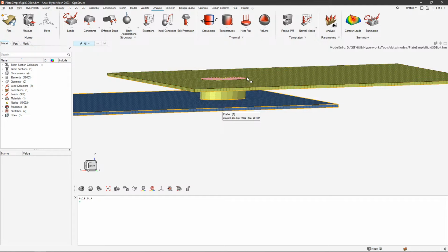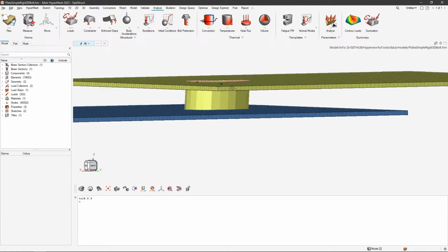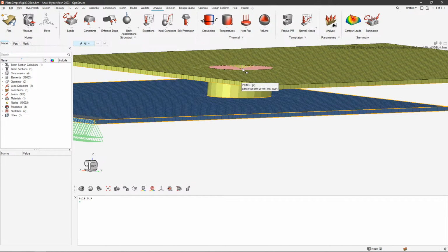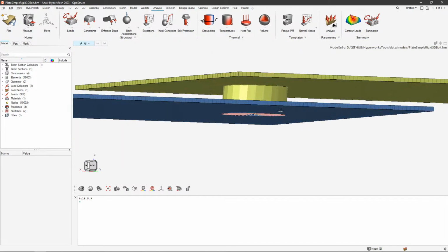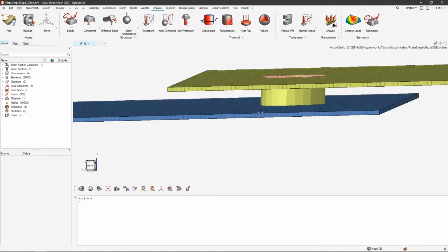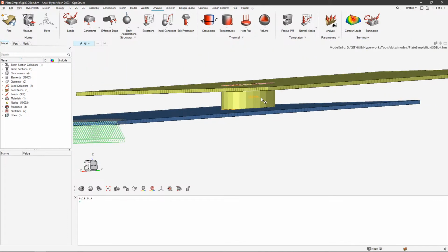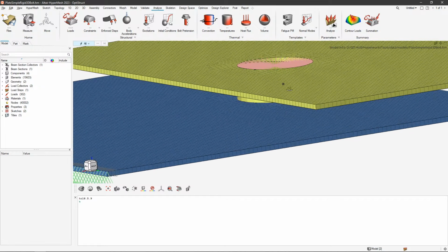And having something like this is maybe even two steps ahead from a detailed perspective, because I can think of something like a C-bush element, which is connecting the master nodes of two RBEs. C-bush elements have spring properties, so you can have a stiffness, but not just as a one-dimensional scalar value; you can have stiffness components in different directions. A colleague of mine told me this is used heavily in the industry.